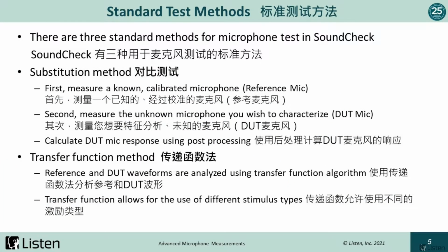Let's go back to our presentation and talk about the next method. And that's the transfer function method, and this is pretty interesting. It's similar to a substitution method, but we're not going to post-process the response curves. We're actually going to analyze the reference and the DUT waveforms.